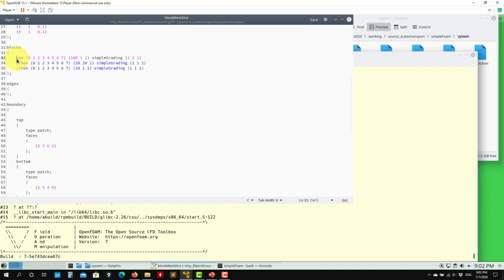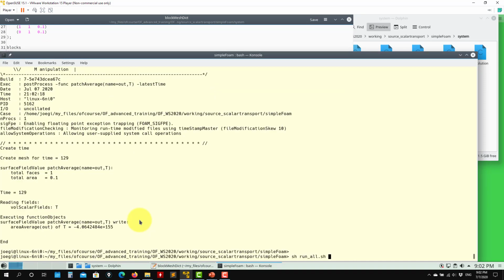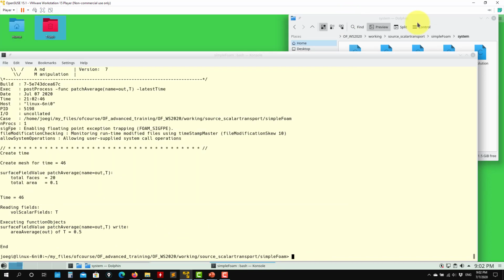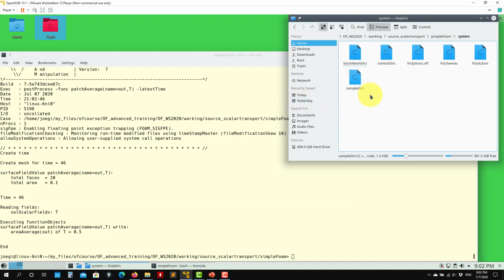Let's go back. I see that there is also no problem working in 2D. You add it this way, and if you want to go 3D, you can do it with no problem. So close here. Let's go to pimpleFoam. The setup is pretty much the same, but now we have the time. Remember that now we control everything using the time step, but you also have the option to add under-relaxation to stabilize everything.